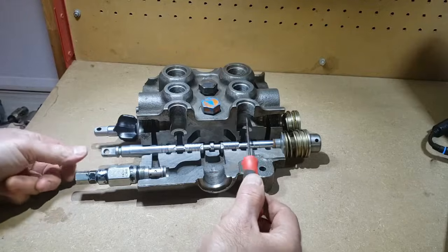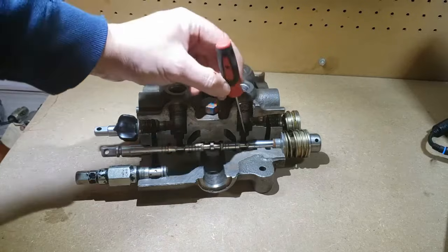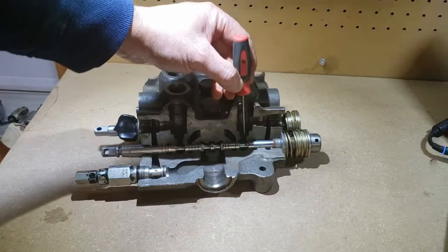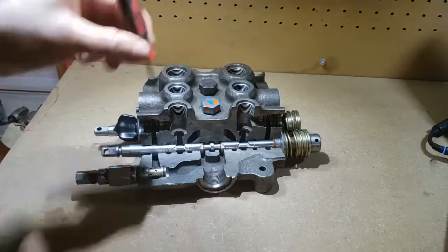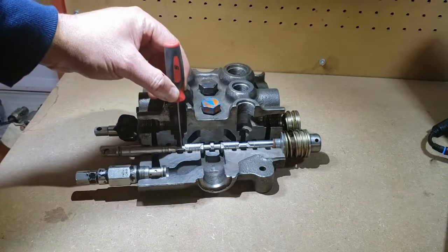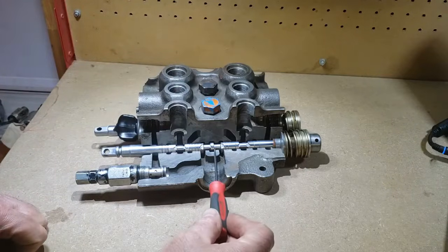So when the spool's in the hold position, oil can come from the work port, get all the way around the spool, but it can't go this way or this way because the lands are tight in the bore of the valve and it's all sealed metal to metal. Same over here. This work port's blocked. So our open center path is open right now.